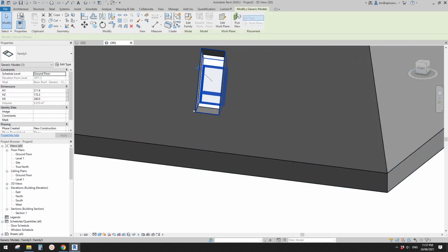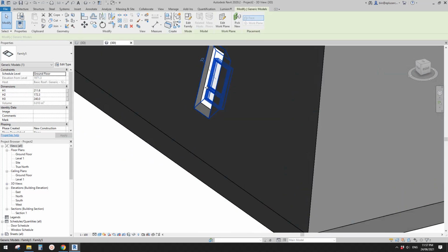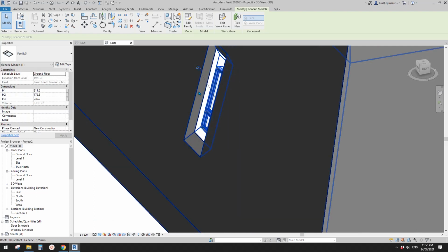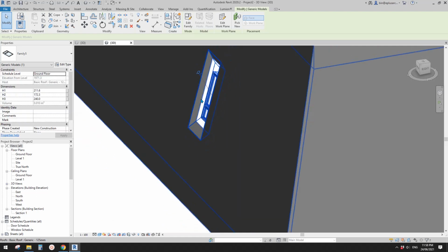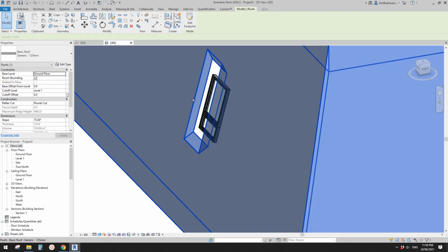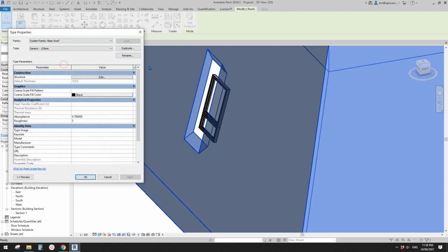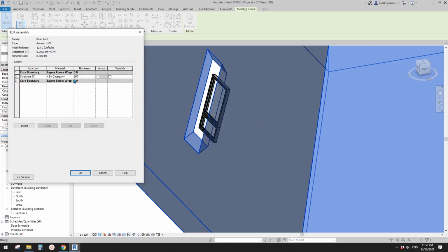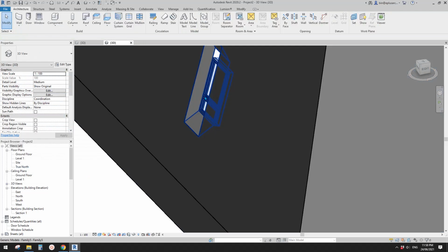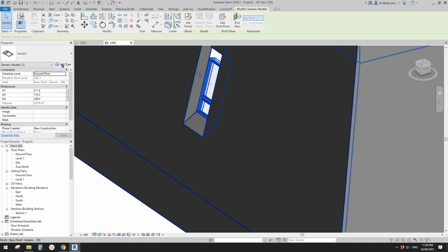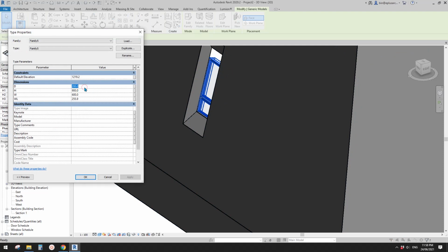select this window, so we can, it looks like the depth, the offset, the set down of this window is too much, because this roof is only 125. Maybe we can just make it thicker. So maybe make it 200. I'll just duplicate a new one and make it 200. And then I'll just maybe make this window, instead of 200 deep, make it 150, something like that.